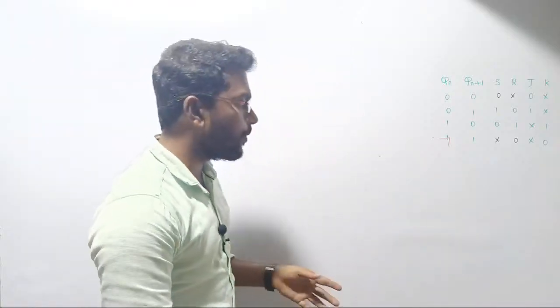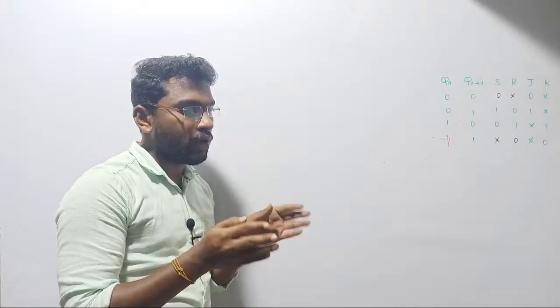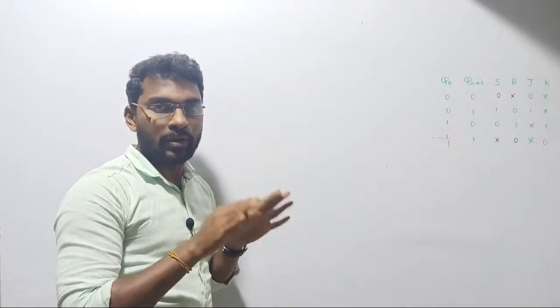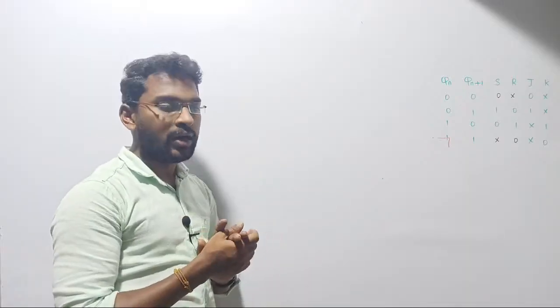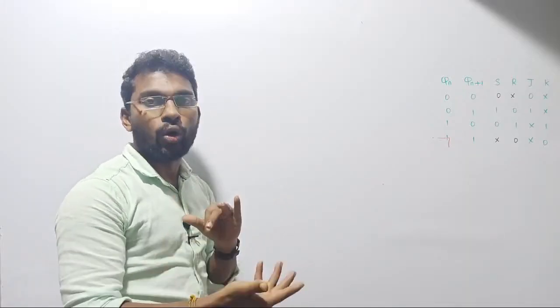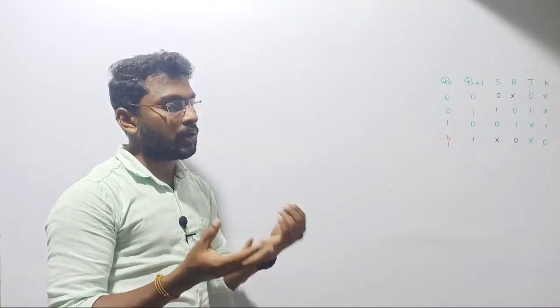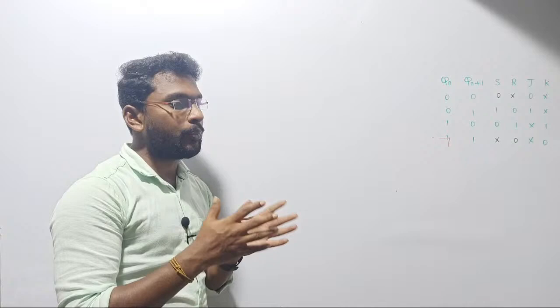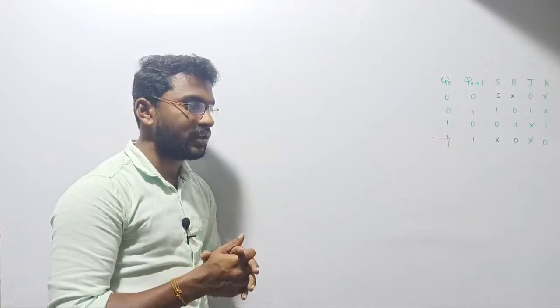So let us take the D flip-flop, right? I hope things are very clear. With the help of a shift register, we are going to store binary bits, right? And we can also transmit the bits from one point to another point. We can also convert the code from serial to parallel or parallel to serial, right? Simply, people call these temporal codes and spatial codes, right? So let me teach you slowly. We'll see all those things, right?